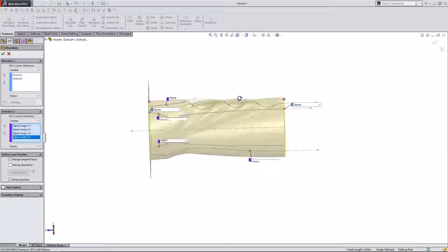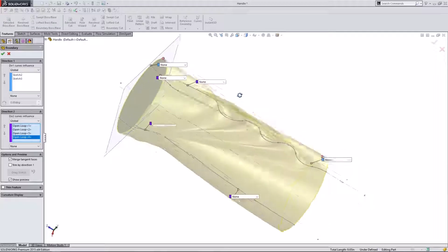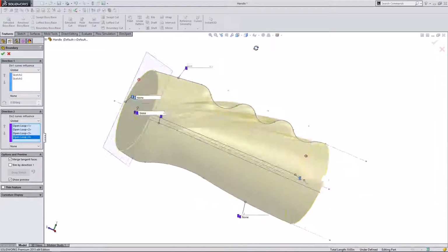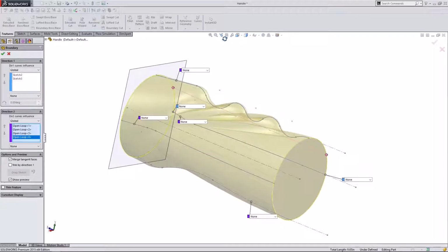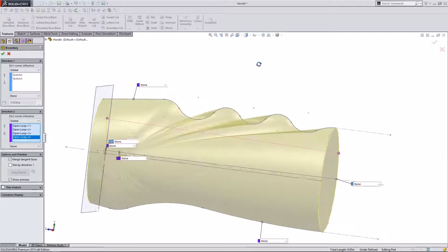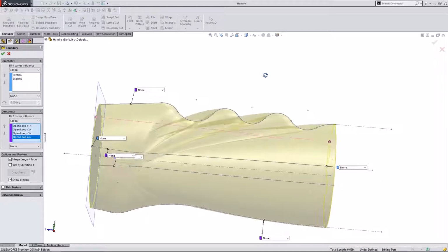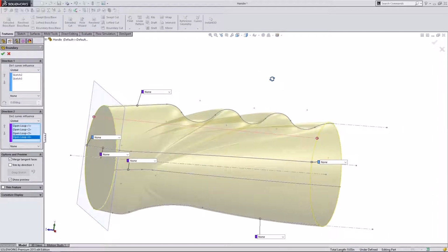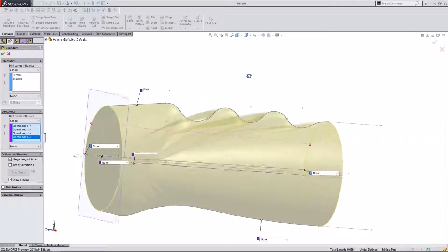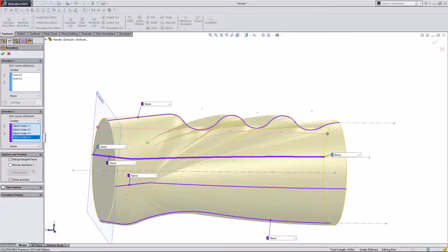So you can see we're running into some sorts of issues here with the surface. So the surface it's really not looking good, and that's because this sort of surface that we've created is kind of like a pantyhose. That's the way that it was described to me back when I was learning. You can stretch it, you can kind of twist it, but you really don't want to get to a point where it's about to rip, because then your part isn't going to be designed well.